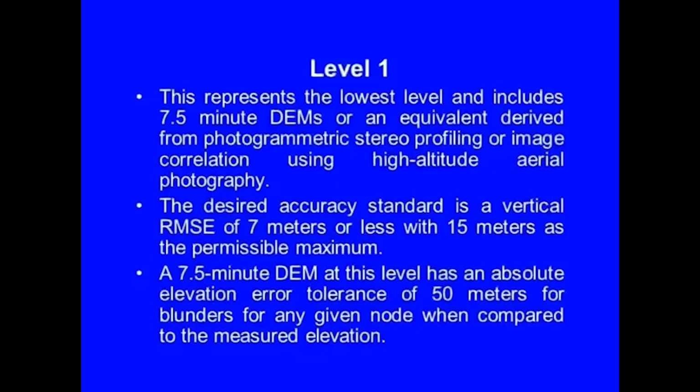This represents the lowest level and includes 7.5 minute DEMs and equivalents derived from photogrammetric stereo profiling or image correlation using high altitude aerial photographs.